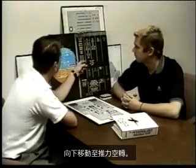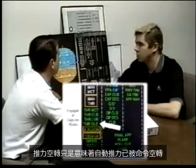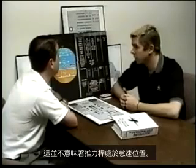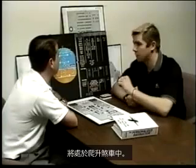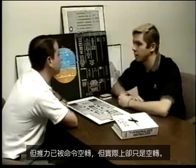Moving down to THRUST IDLE. THRUST IDLE just means that the auto thrust has been commanded to idle thrust and idle thrust only. It doesn't mean that the thrust levers are in the idle detent. Typically, the way we operate this aircraft, the thrust levers are going to be in the climb detent. But the thrust has been commanded to idle and nothing but idle.